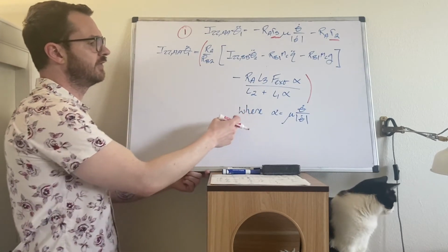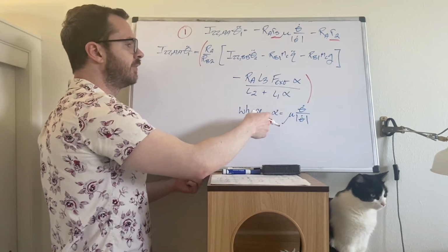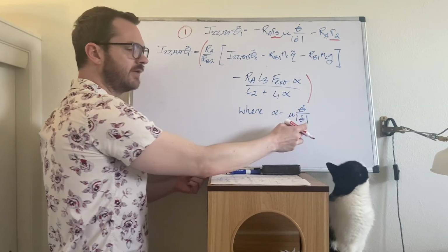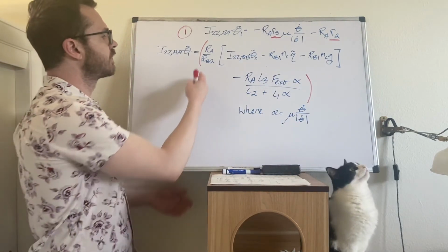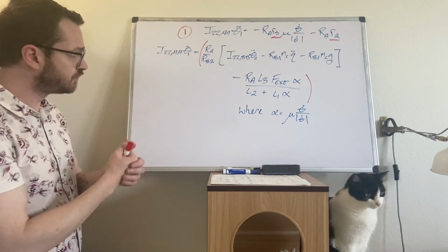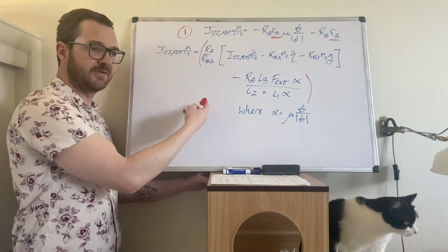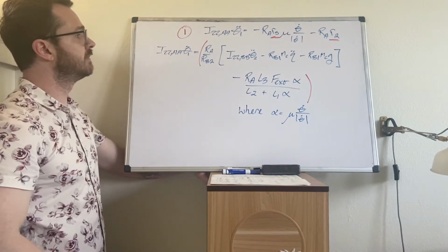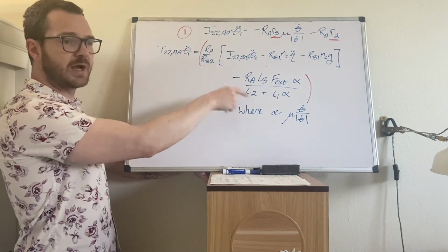And what I've also done is one replacement. I've put in an intermediate variable alpha, and I'm letting alpha represent mu theta dot over magnitude theta dot. So this term now, right, this is our equation of motion. So we ask ourselves, are we done? Is it scalar? Yes, it's scalar. We had 1 degree of freedom, right? We have one equation. Have we eliminated all the reaction forces? Yes. This has no reaction forces in it.